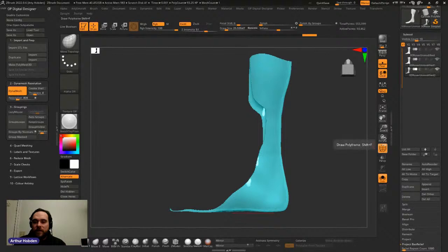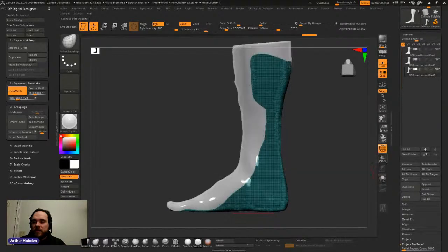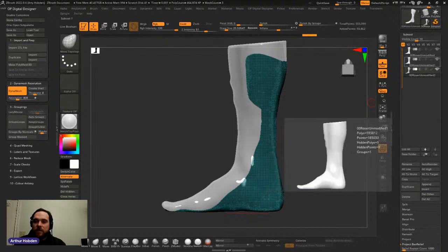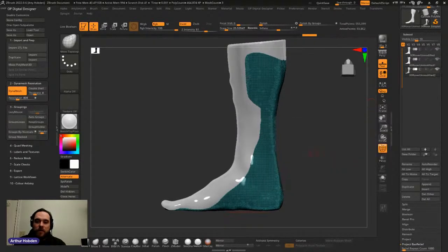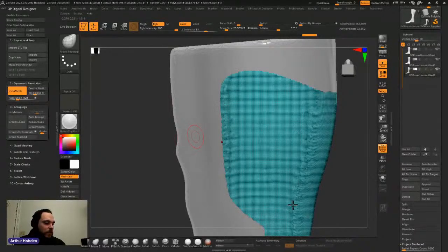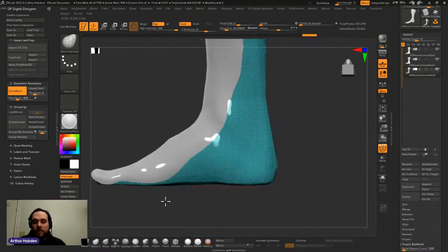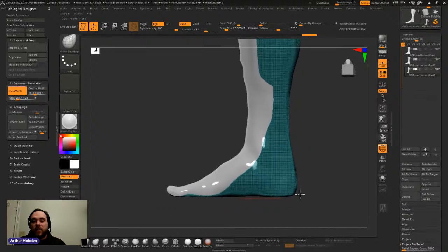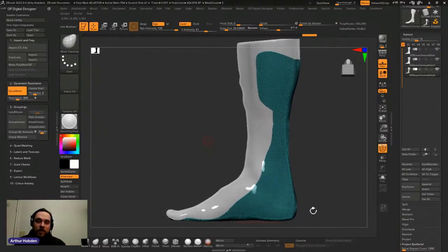So what we have here is, on a separate part, we have our isolated surface. Above that, we have our scan that's been cleaned. And above that is the original. So we're about ready now to take it to the next step, which is we got to convert this messy mesh that we've remeshed into a quad mesh for CAD. Quad meshes are the secret sauce that combine mesh editing and mesh modeling with CAD workspaces. If you can find a way to do quad meshing, you're going to be in the game very quickly.